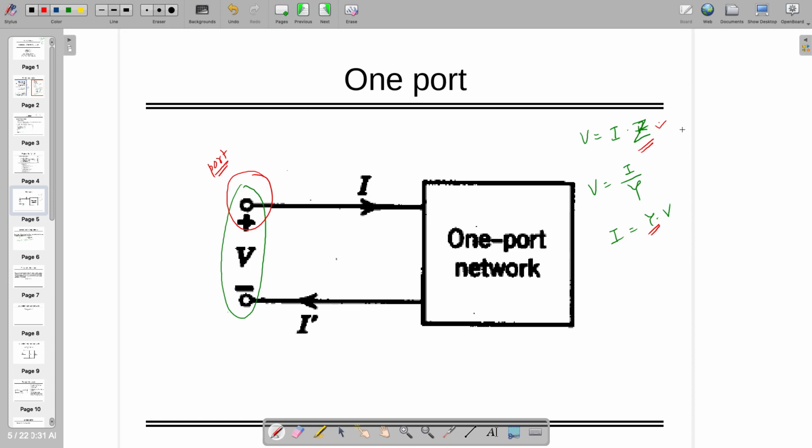If you remember, I told you, if you want to connect two circuits, two one port networks are available. If I am connecting this point to this point, if the input impedance of this one is low, then maybe this voltage node cannot drive it, and you have lower voltage than what you are expecting. This is also known as loading effect, right? So the driving point impedance is the most important, because this node is going to drive the next node.